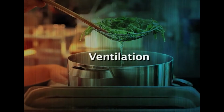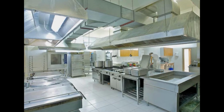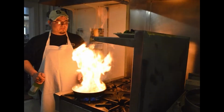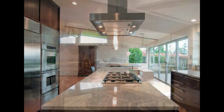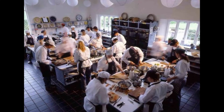Next, another important aspect is ventilation. Ventilation is very much important, because a large number of people will be working in a small area, and apart from that, you have the heat that is generated from the foods when they are being cooked. So cross ventilation should be maintained, so that fresh air is circulated and carbon dioxide filled air is removed from the room, and the people will not have any sort of exhaustion.